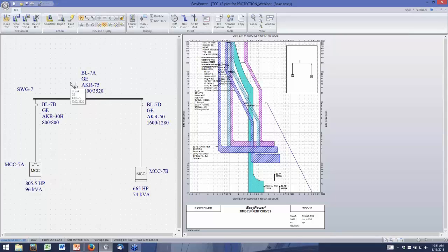But if you are trying to spend the least amount of money, you'll put a ground fault device only on the main, and you won't put ground fault on the feeders, and then it becomes a bigger coordination problem, because now for a ground fault down here, you're at risk of losing the entire system. That's completely preventable if you put ground fault on these feeders for that small additional cost.